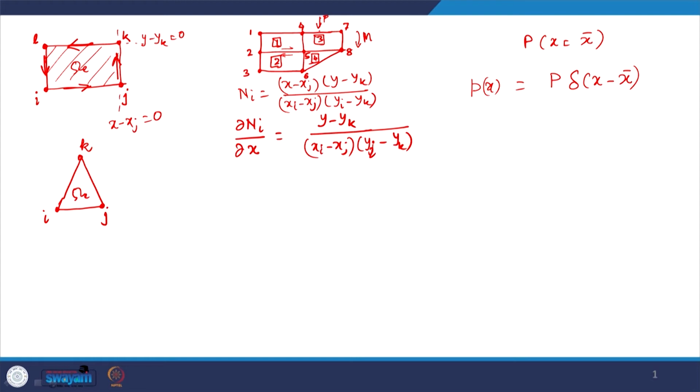So, in this particular case it would be 225, because this is where the x is ranging from, and this is at 75 plus 150. So, this is 150 and this is 75. So, together it is 225. So, it would be x equal to 0.225 meter. So, x bar is equal to 0.225 meter.